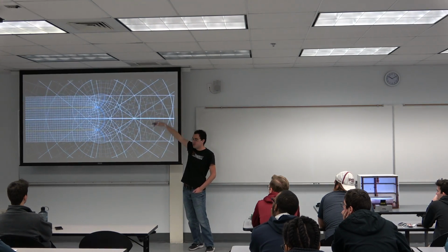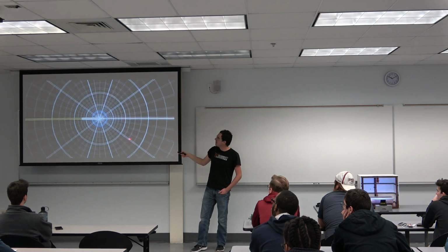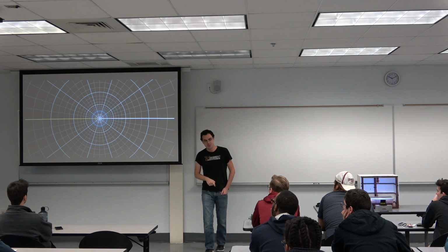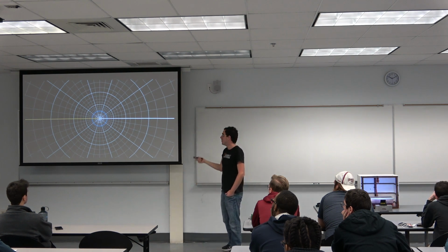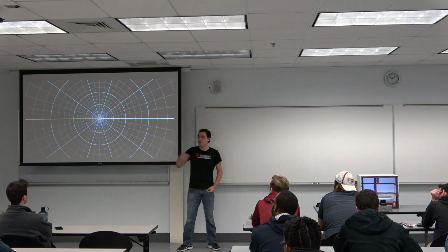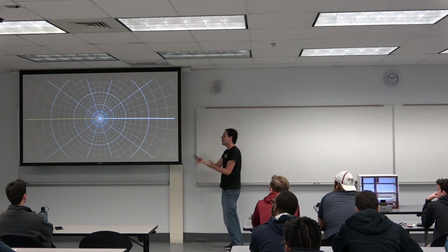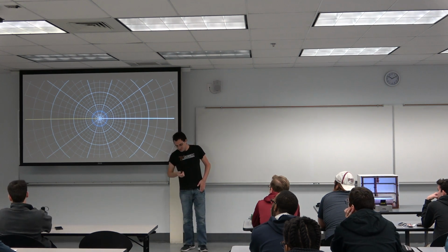And this happens over and over. I'm showing only two folds in the folding diagram, but they land exactly at the same point. And this kind of proves that the Nyquist sampling theorem actually comes from the Z transform, and it kind of ties everything all back together.